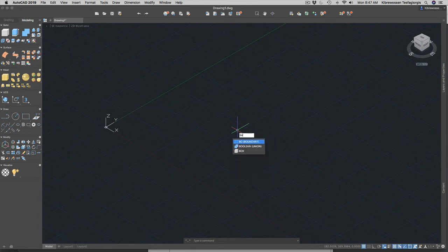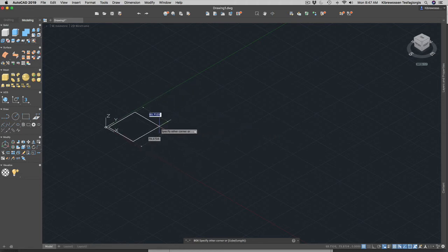So I'm going to restart my box operation. Then my first coordinate was 4, 3.5. Make sure that, unless we are told otherwise, you start with a conventional x, y, z coordinate. See, x is in this direction, y is in this direction, z is on top. Okay, then next is length. When you do the length, make sure it's precisely along the x-axis. Then that is 3.5.